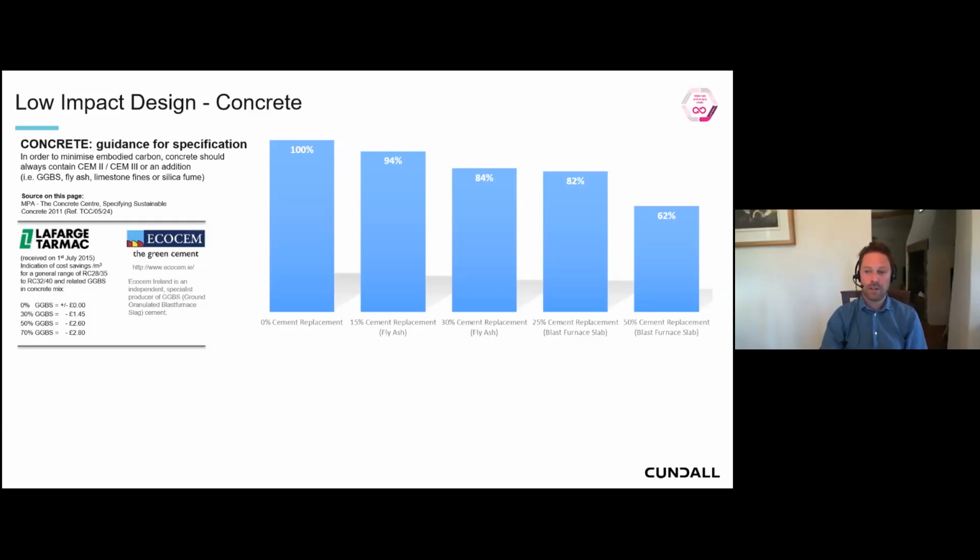Because you're using waste products, it tends to not come at a cost premium, but it does have some program impacts because the strengthening rate is slowed down. And that's something you need to consider, and you need to think about the blend of how much cement replacement you can utilize whilst not negatively impacting the program, and that'd be different for different components.